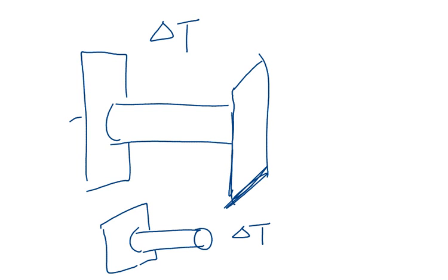So this is very funny compared to what happens when you apply forces, right? When you apply a force to a rod, you get a stress. But look what happens here. When it comes to forces, a stress results in a strain. So you can't get a strain without a stress. But in these two cases here, dealing with temperature change, if you look at the bottom case, is there a stress if all you apply is a temperature change? There's not, right? There are no forces. So even though there are no forces, you end up with a strain. So in the bottom case, you get a strain without a stress.